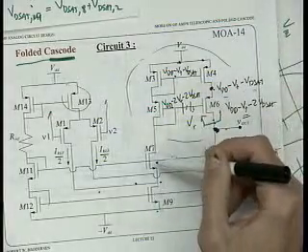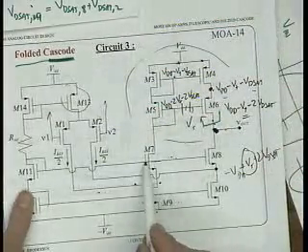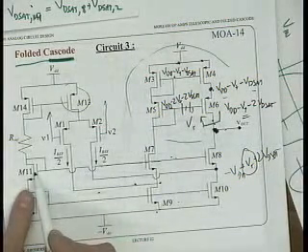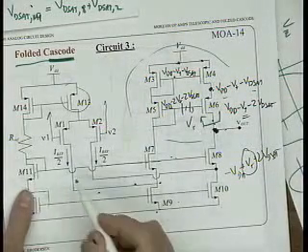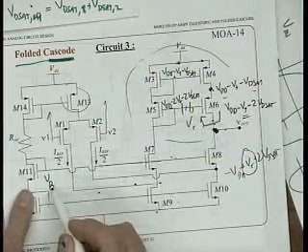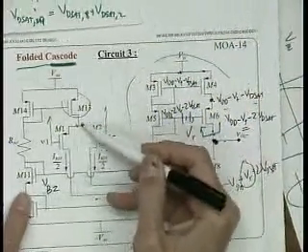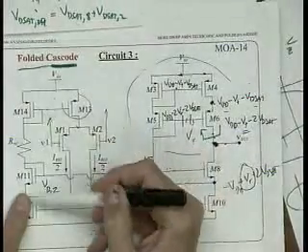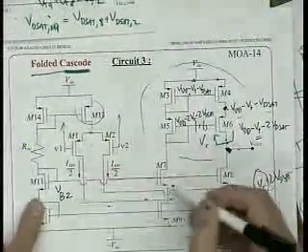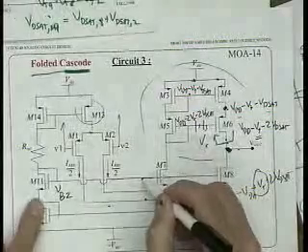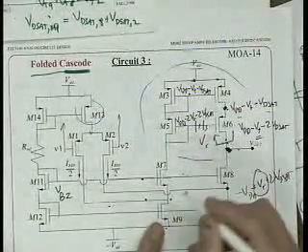Well, look where it's connected. The gate of M7 goes over to M11 here, right? So this is a DC bias voltage, VB2. It's not connected to anything to do with that voltage right there, right? So it's set by this swing right here. And the trick is we'd like to set this voltage with bias 2 so that, where should it be set?